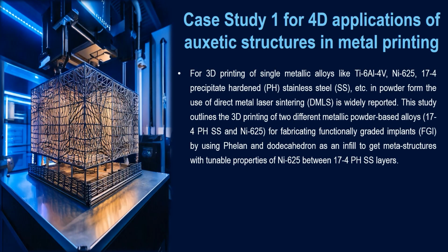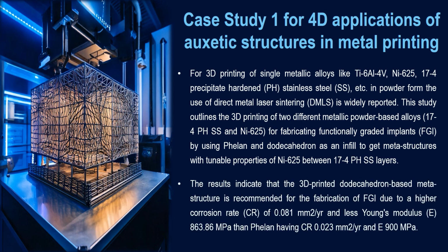Now, let us see one example in the form of a case study, where we are interested to develop a typical exotic structure in 3D printing application involving different metallic alloys. In previous reported studies, people have used titanium based alloys, nickel based alloys, stainless steel based alloys, and their powder for making a functional prototype using laser powder bed fusion.